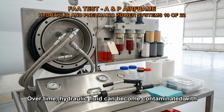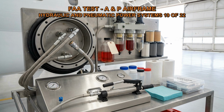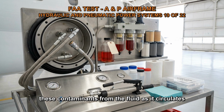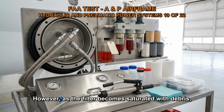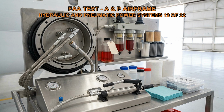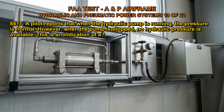Over time, hydraulic fluid can become contaminated with dirt, metal particles, and other debris that can clog or damage hydraulic system components. Porous paper filtering elements are designed to remove these contaminants from the fluid as it circulates through the system. However, as the filter becomes saturated with debris, it becomes less effective and may even restrict fluid flow, leading to system malfunctions. To prevent this, filters should be replaced at regular intervals as specified by the manufacturer or maintenance manual.